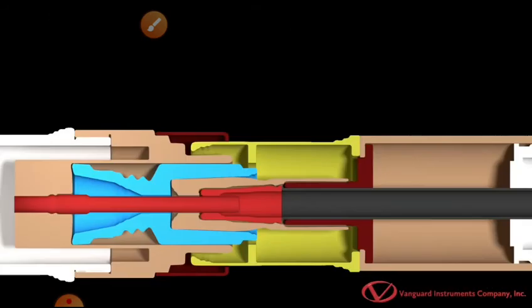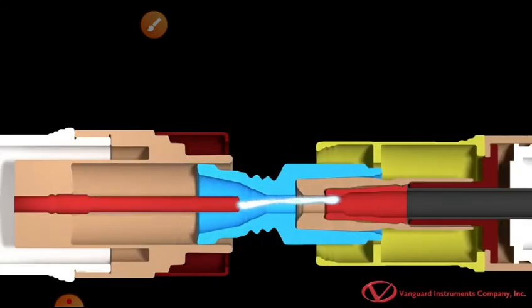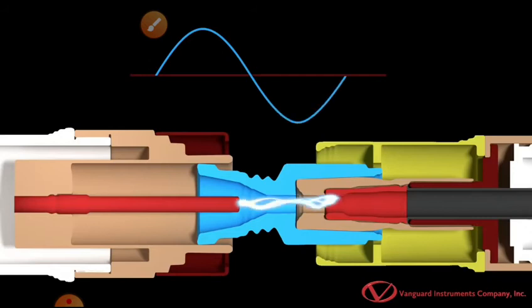When the mechanism's contacts open, an arc is created due to current interruption. An AC arc extinguishes at every zero current level, but reignites immediately after crossing the zero point due to the presence of voltage across the open contact.